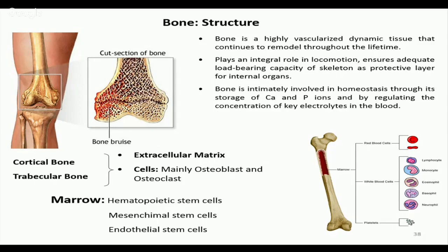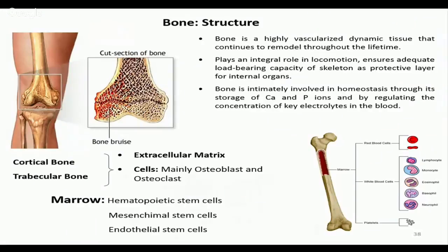And as we know, bone is also piezoelectric. Bone is a piezoelectric material. We will see later on, if time is there, a little bit why it is piezoelectric, because it is hydroxyapatite, which has a hexagonal close packed structure, and as it deforms, there is a charge separation that eventually gives you piezoelectricity. So as they are piezoelectric, this buckling and then elastic bounce back helps.